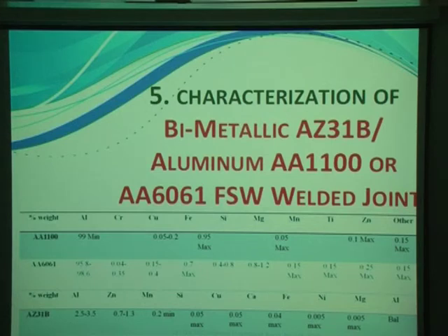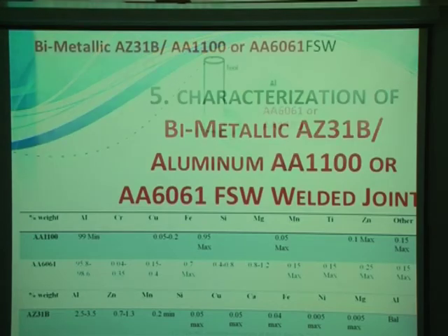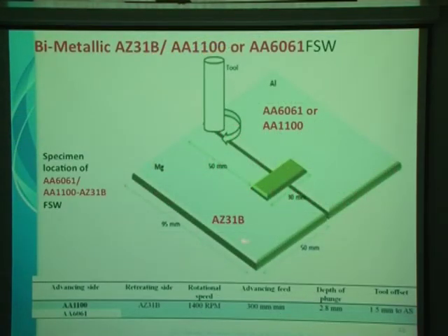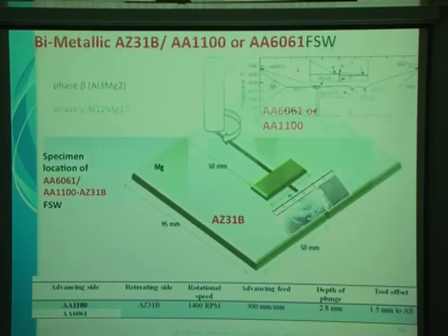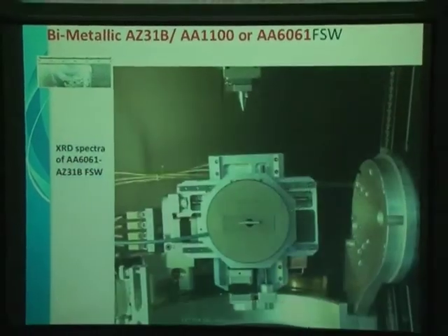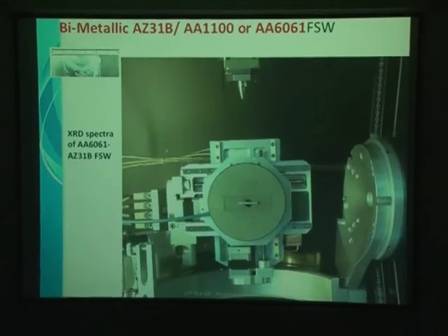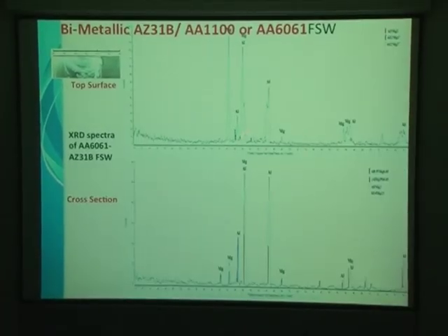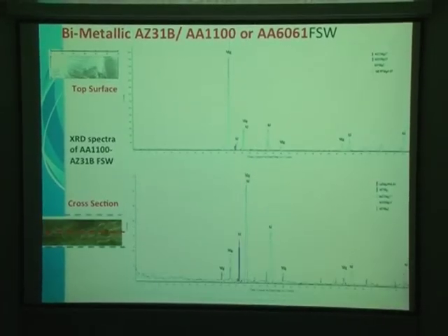So we picked some aluminums. For example, this is almost pure aluminum. 6061 is very common in structural parts, so it makes sense. And we married this to the AZ31B alloy, where aluminum is a main component. You take samples from this and look for intermetallics. You take slices, use the SEM, do a lot of analysis, you take the XRD, this is the sample right there, and you do XRD measurements to back out the bimetallics,